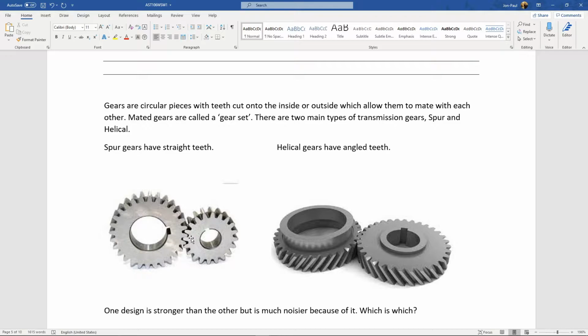On our manuals, what we're talking about today, if we have 6 forward gears, there will be 6 sets of 2 gears. When I shift the transmission into the gear ratio that we like to call first gear, these 2 gears get meshed together, my input gets changed because of this gear ratio, and now the output coming out of the transmission is whatever gear ratio.